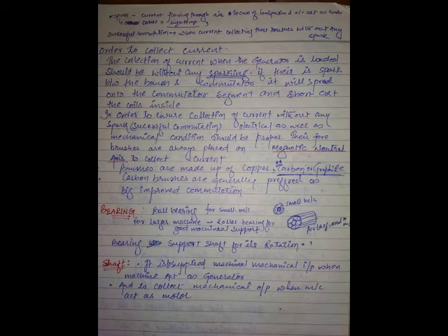You are starting with 1, 2, 3, 4, 5, 6, 7, 8, 9, 10, 11, 12. For your easy understanding, I am giving numbering to you. Let us take, there are 12 slots in the armature. It is a 2-pole armature. What is pole pitch according to definition? Can we say 6? Pole pitch is nothing but 6, because 12 by 2 is 6. Now this is the pole pitch.